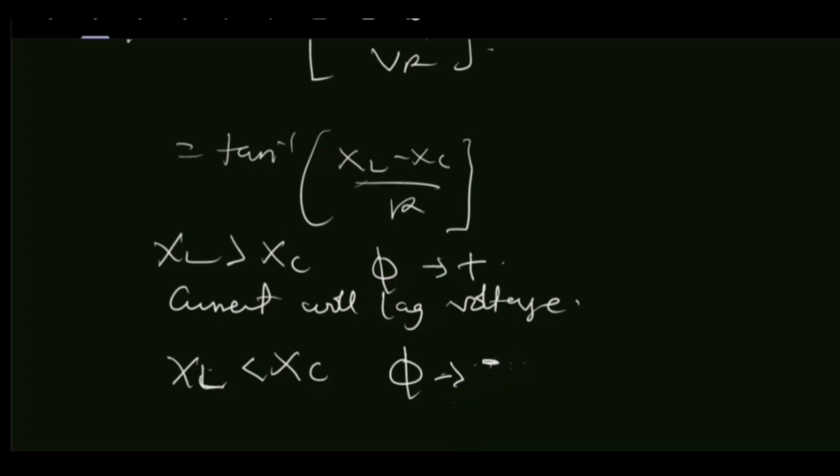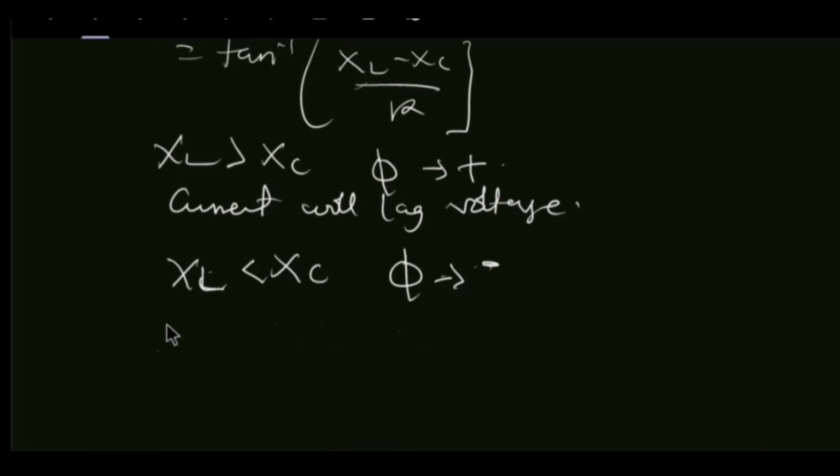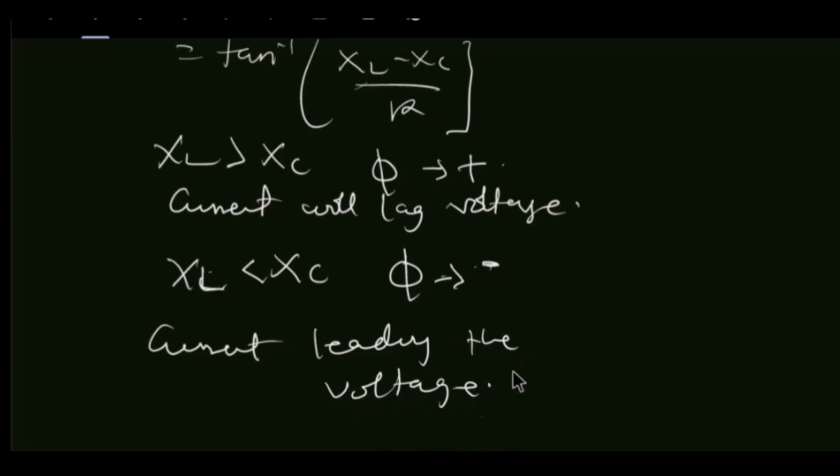And what does that mean? This means that the current is leading the voltage. And when a current is leading the voltage, it means that the reactance is capacitive in nature.